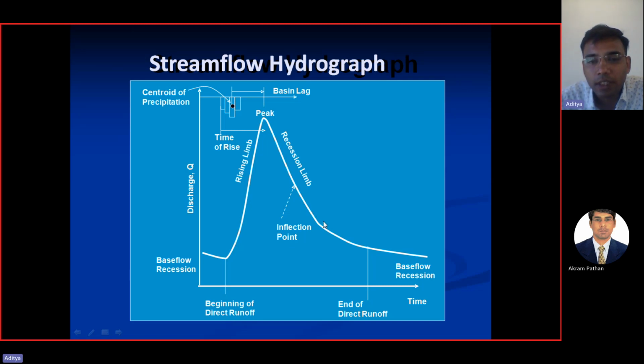It again reaches a normal level after the rainfall stops, and you get the hydrograph of a particular instant. If you neglect the initial abstraction, that is base flow, infiltration, phi index, W index, you will get the direct runoff. This hydrograph, or runoff, is used for different hydrological applications.